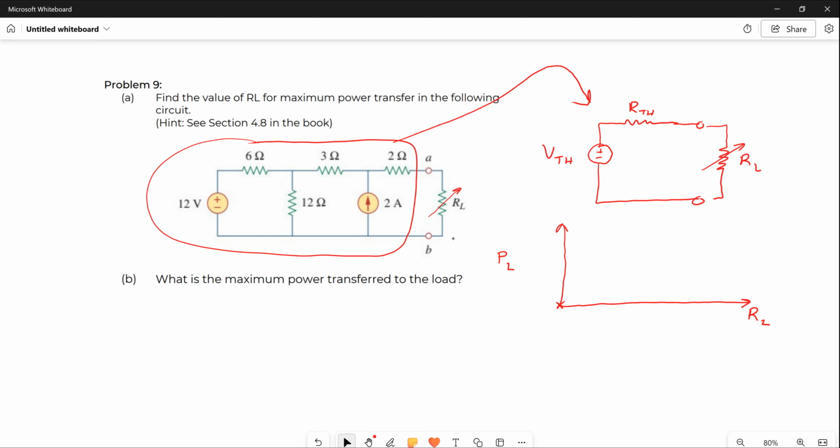You make it on the other end of the scale. You make it infinity, and then the current goes to 0. If it's an open circuit, and you're real high in the load resistance, so I squared R, or V times I, is going to tell you you're back to 0 again. The question is, what does it do in between? Well, it does this. Again, I have this in another video. It reaches a peak and then it's asymptotic like that.